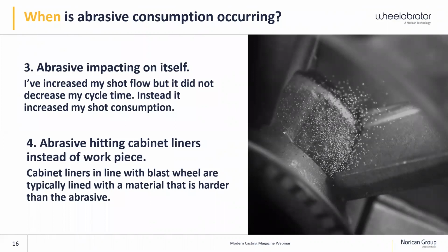Another time when abrasive consumption is occurring is when you're just missing the part. My abrasive is hitting the walls, the cabinet liner, or something like that, and it's just not hitting the part. It's not aimed or targeted correctly.